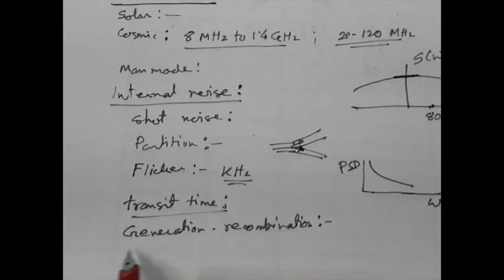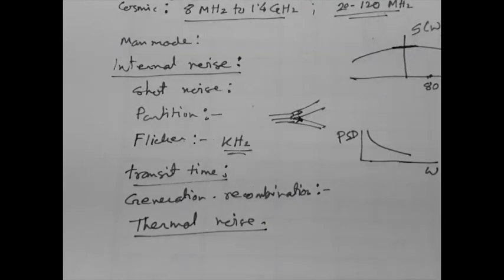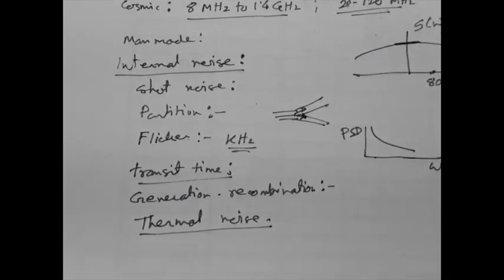Next, we will try to understand thermal noise. This arises due to the random motion of free electrons in a conducting medium, such as resistors, and actually anything. Each free electron inside a resistor is in motion due to its thermal energy. The path of individual electron motion is random and zigzag.